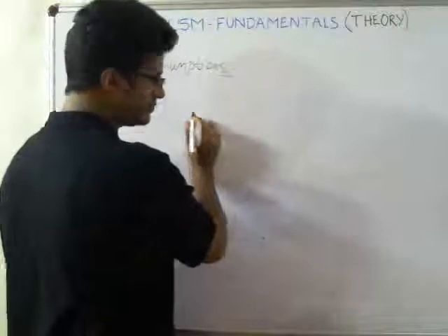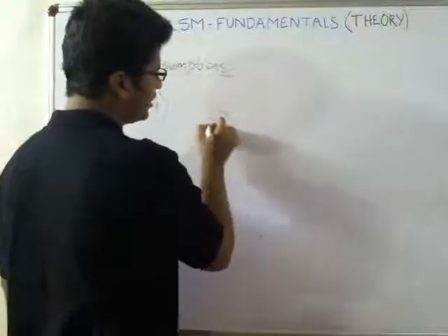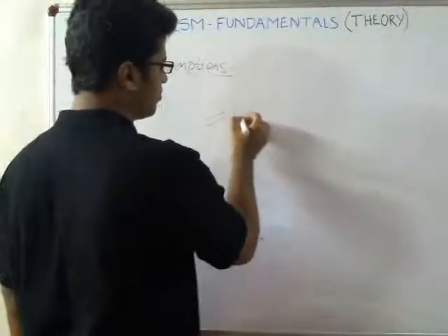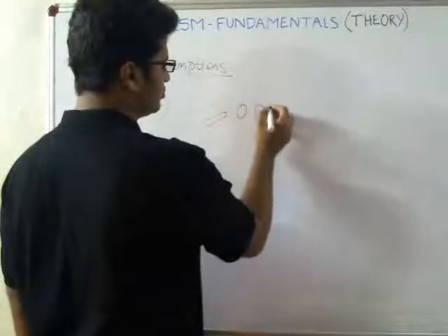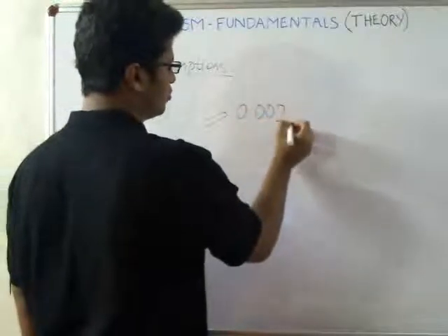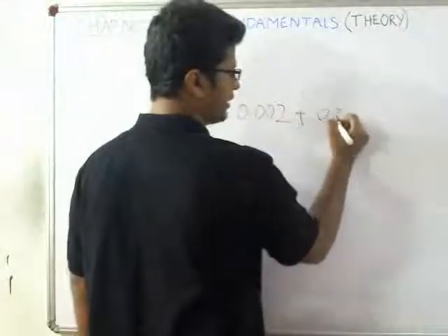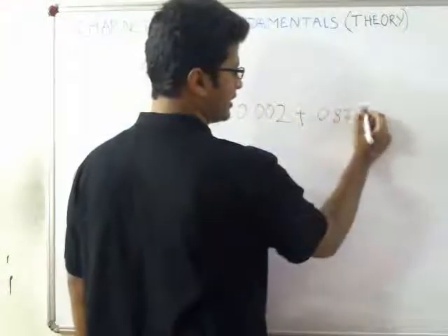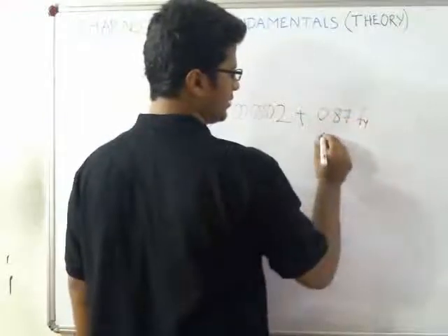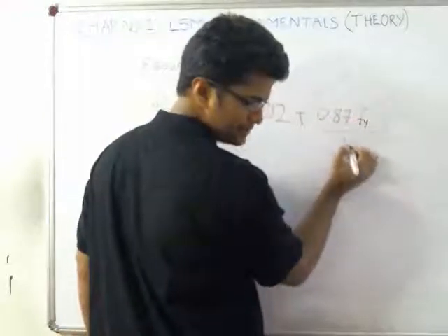The strain should be greater than or equal to 0.002 plus 0.87 Fy on Es.